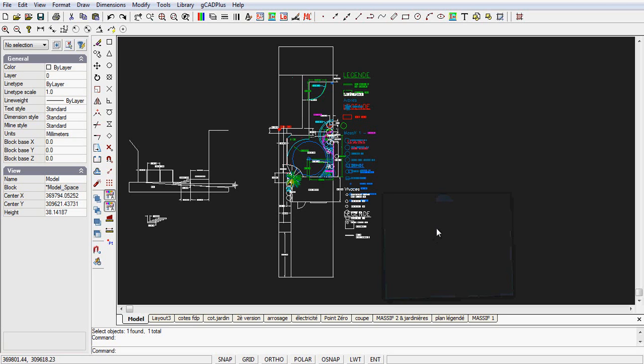We really need to change the size of this drawing. We want to move from meters as a base unit to millimeters. The reason for that is that we want to be able to use our library of plants and standard symbols and size symbols and so on, and our details, and we want to be able to bring them into the